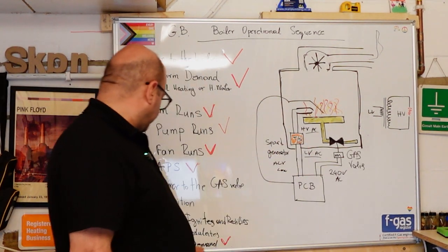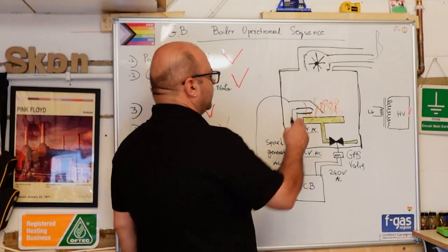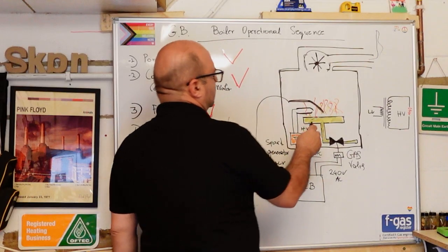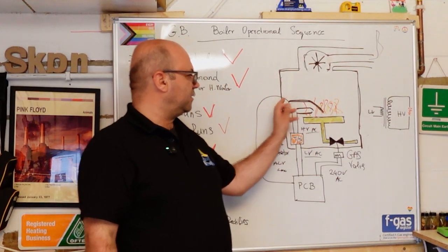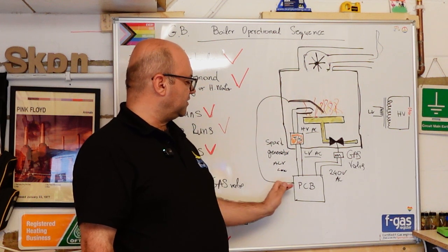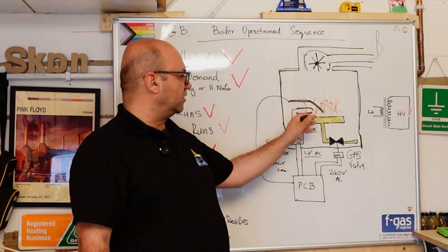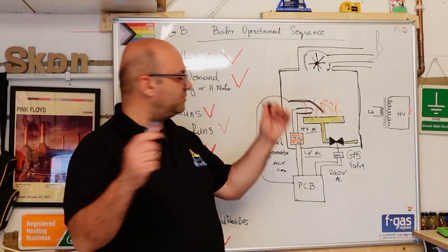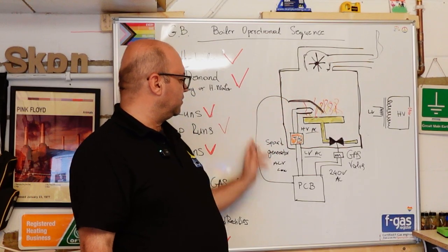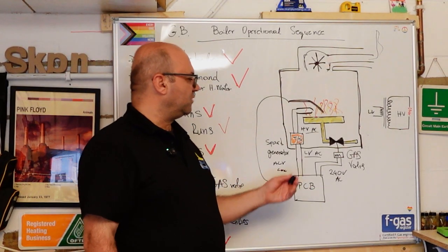Rectifies, we're not going to go into the burner modulation here, but just to let you know there is another probe here, which we will speak about extensively in a second, which we call the flame probe, and this one sends a signal to the PCB to say if we have flame or not. This flame sensor, the flame probe or flame supervision device, is just a little metal piece here with a cable which transfers information to the PCB. We will speak in a minute about how that works.